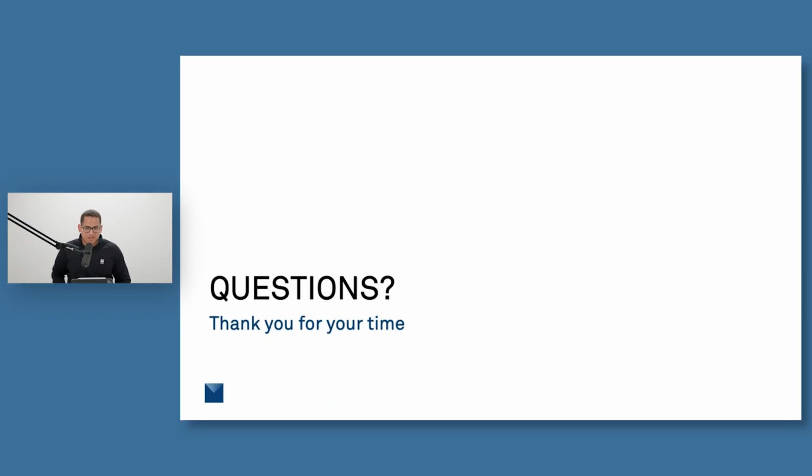Yeah, so this is actually a topic that I've hit on in the past as well. In some of our past webinars, we talk about the differences between lab and field methods. You can do that, and you can take cores too at deeper depths. That way you have at least an intact sample to take back to the lab. And the challenge, of course, is in the lab with that. What I love about the lab methods is we can isolate specific areas that we're trying to measure and understand these individual layers and what they're contributing. The challenge is in the field, we're looking at the whole interaction of those layers, whereas in the lab, we're looking at isolated portions of the soil.